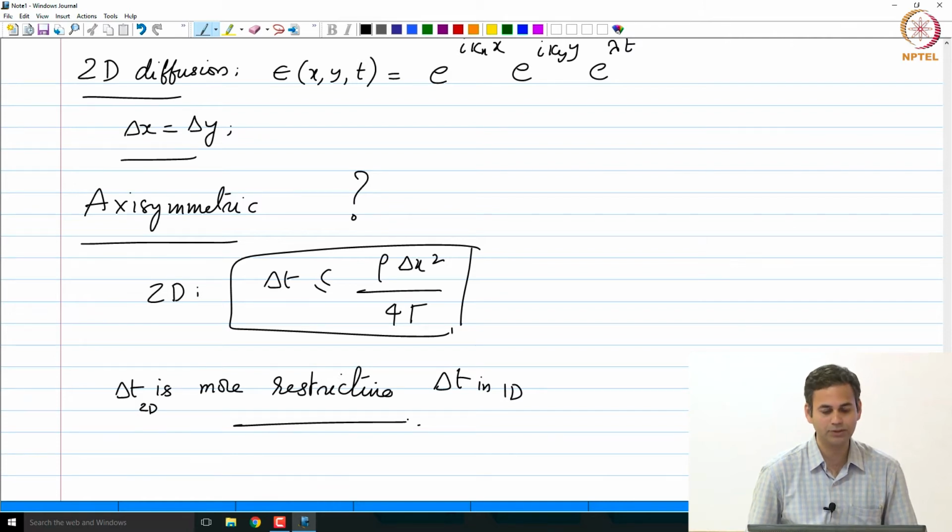As you can see, this entire process of the stability analysis works only if you make a lot of assumptions like constant coefficients, no source terms, uniform cells and so on. So, you can clearly see the complexity if these are not met. As a result, we can only apply it to simple problems, and for practical problems of complex nature, we cannot really apply this.